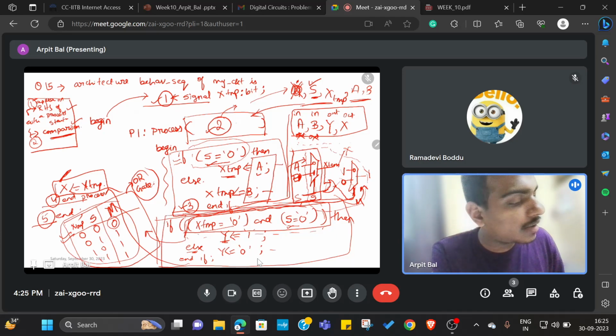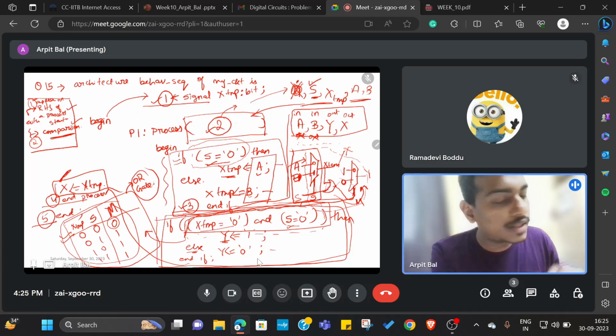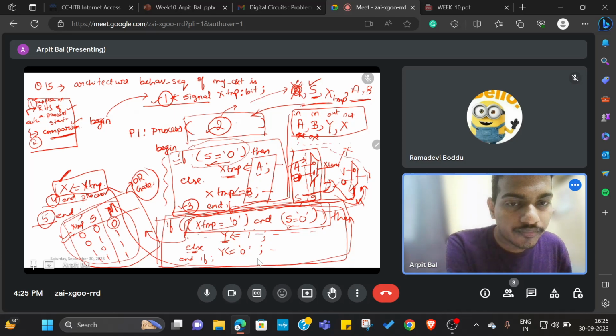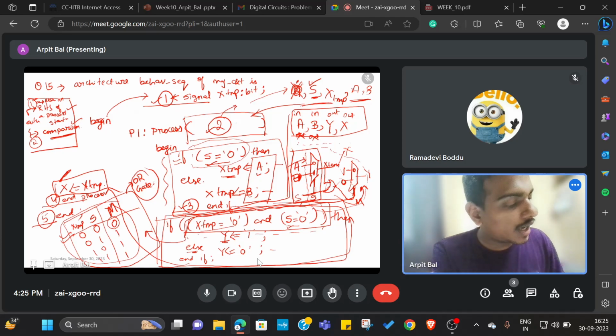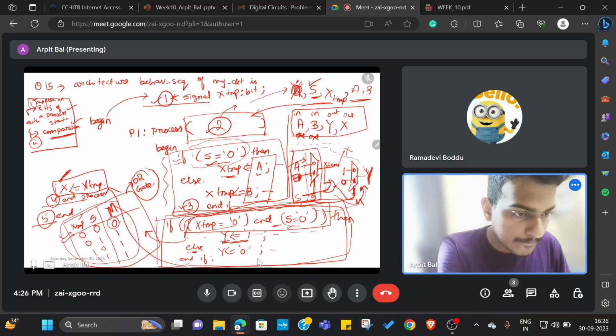So if we use an OR gate and we connect it to another multiplexer, there is another if statement, right? So this if statement will give rise to another multiplexer. If that signal M is 0, then y is equal to 1 will be selected. If it is anything else, it means if it is 1, then y is equal to 0 will be selected, and the output here is y. Okay, is this clear? Yes, Bhaiya.